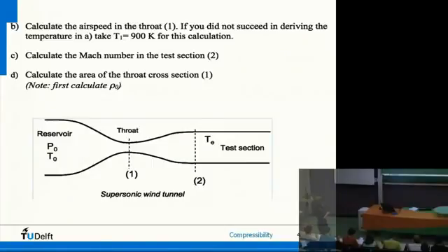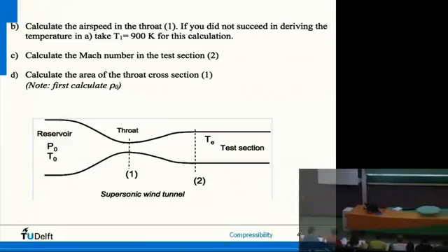This is a picture of the case. So we have a very large reservoir up here. Flow is going out into the throat. I also got a question, how can the speed be 0 in this large reservoir? Well, you can assume it to be really huge and this to be very small. And of course, in some bit of the reservoir, flow will flow out, but the very large bits don't really notice. So you can approximately assume the speed to be 0 inside the large reservoir.